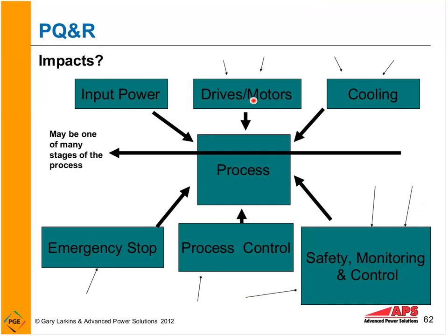Also, break down what is failing. Does my adjustable speed drive maybe give me a trip code saying over voltage or under voltage? It could be the emergency stop relay, a simple little relay that I might be able to replace with a more tolerant relay. And if you modify controls, please be careful of the safety concerns around controls. So in many cases, I don't have to go treat all the power coming into the facility, treat a whole feeder. Sometimes I can go out to the controls and just treat a few amps worth of power by working on the control system. So it's important we look at what's going down and why.